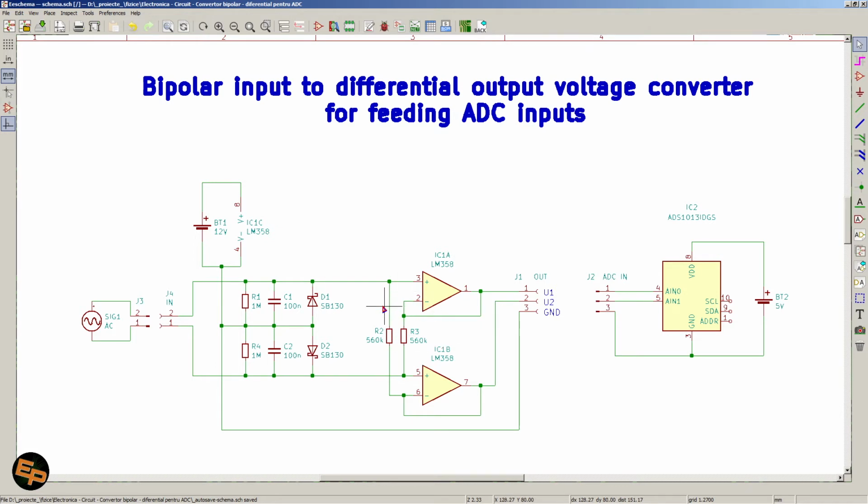I felt the need to put these resistors between the minus of each op amp and the plus input of the other op amp, because they provide a little bit of extra stability. Without any component, the circuit is unstable and also has the risk of receiving short negative voltages on its input, which causes the so-called phase reversal on the output of the op amps.